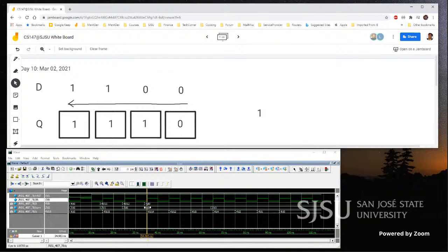And since we kept that left shift signal alive also in the next clock, this guy is thrown out. This shifted here, this shifted here, this shifted here, and this is duplicated. So this has become 12. And thus in the next cycle, this guy is shifted out, this guy is there, this is left shift, and duplicated. And that's the 8. So this is the 8 value we are getting.